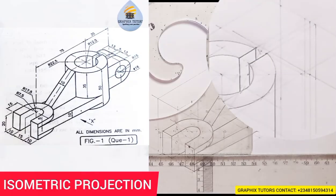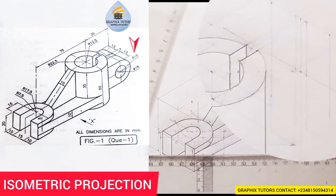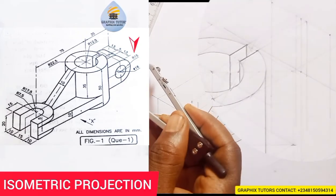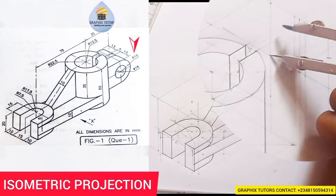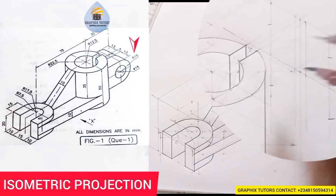So what you do is the thickness, the radius there is given to be 15. As you can see from the diagram, we have 15 there. Diameter of that circle arc here is 15. So just take your compass and you measure 15. So from 0 to 15, then you place it here. You mark 15 up and you mark 15 down. Can you see that? And also come here too. You mark 15 up and you mark 15 down. Can you see what I'm doing?